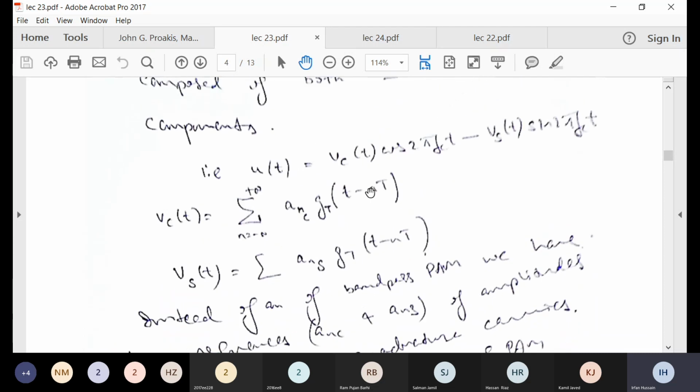Now, the complex number is always used when we want to represent two things. For example, in electrical engineering, networks or circuit networks, we use complex numbers because we want to represent two things. We want to represent the amplitude, and we also want to represent the phase, or the phase delay or the lag or whatever.